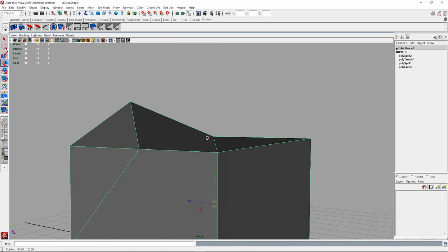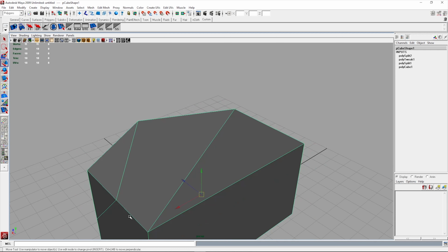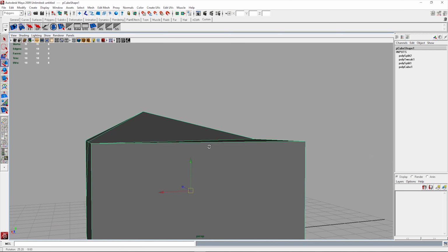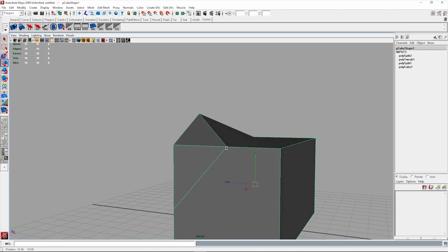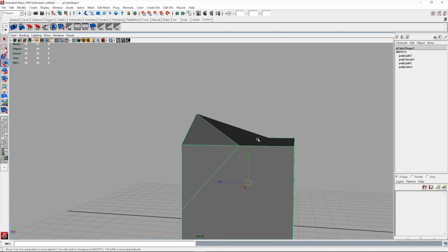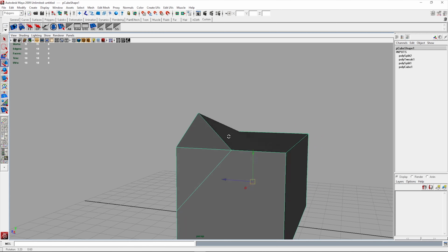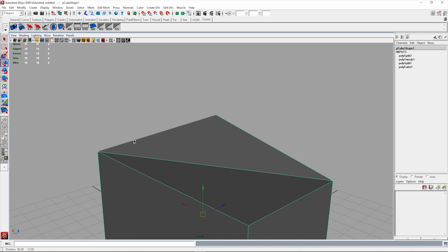But there's something wrong here, see? Well, you've got a quad there, a 4-sided face, which we call a quad, and then a tri, which is 3 edges to define a surface. See, I need to further define this one because this corner point and this point that's highest need to have something defined between there or along.